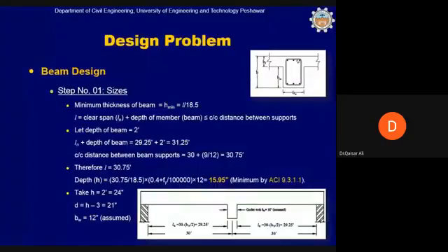How do we assume this 24-inch beam instead of 16-inch? How do we know this? We have tried to explain this in some of our lectures. This depends on many things. This depends on the availability of the formwork in the market, because sometimes, for example, if you want to assume a 20-inch beam instead of 16-inch, let's say you want to assume a 20-inch beam. So with a 20-inch beam, what will happen? 6-inch part of the beam will be inside the slab, and 14-inch will be hanging.